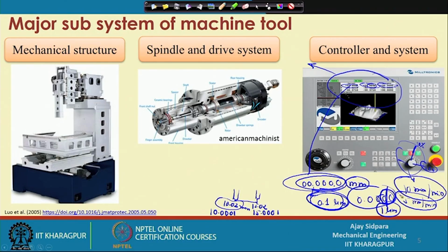So, without changing a part program, you have an option or flexibility so that you can change the feed rate during operation. These things are mostly useful in the conventional CNC milling machine, where we have a possibility to correct things during operation, but we have seen in the introduction section that hardly any noise comes out of the machine, and visibility is almost 0, you cannot see anything, you cannot hear anything.